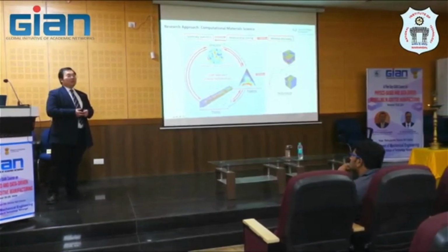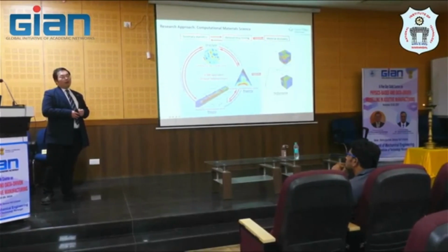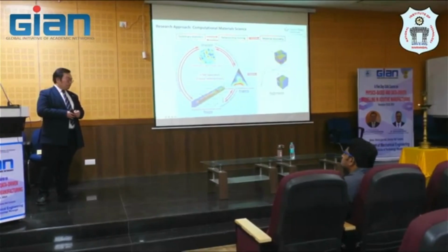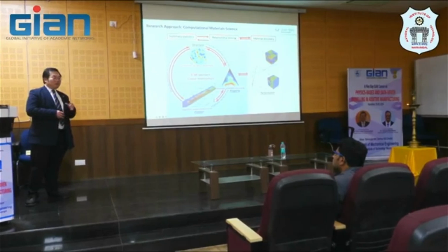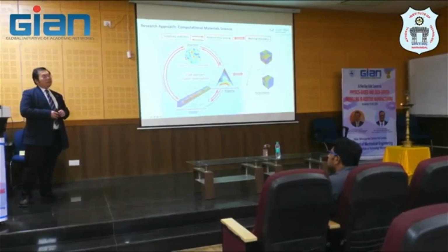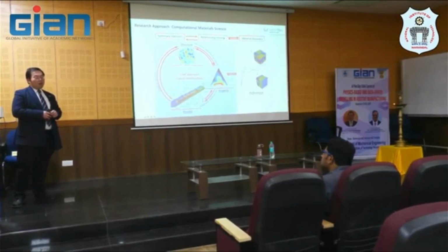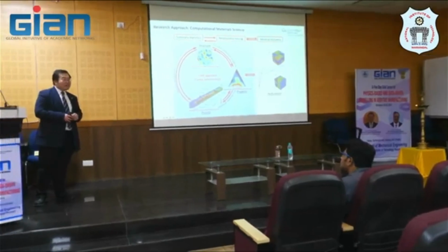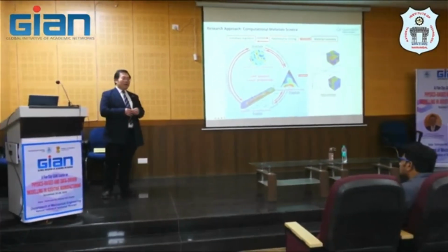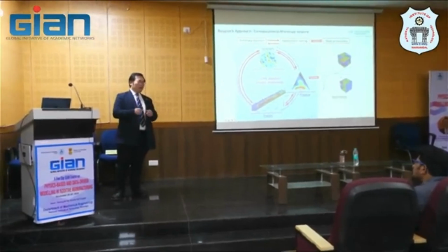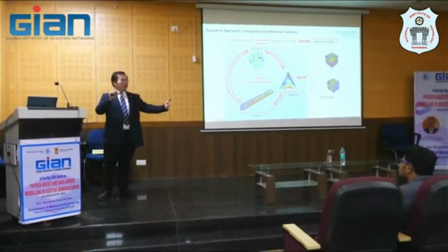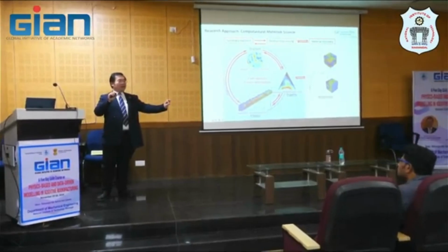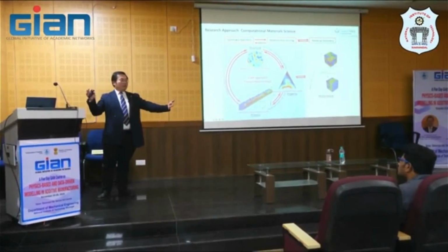The morphology also contributes to gas trap porosity formation, because they have less surface area than spherical, because it's elongated, right? It's actually away from circularity.